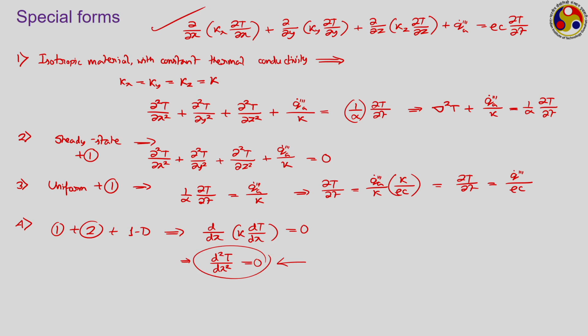Actually, one assumption that I have not written that I should have added here also, that is no heat generation. Heat generation is absent in most situations. Very rarely we find a practical application of conduction with it, like the example of nuclear fissionable material that I have given. There only we can have significant heat generation, otherwise it can be neglected in most situations.